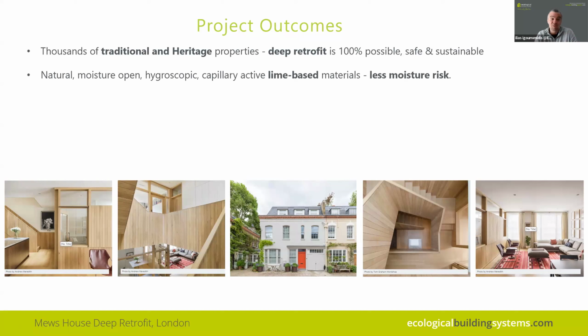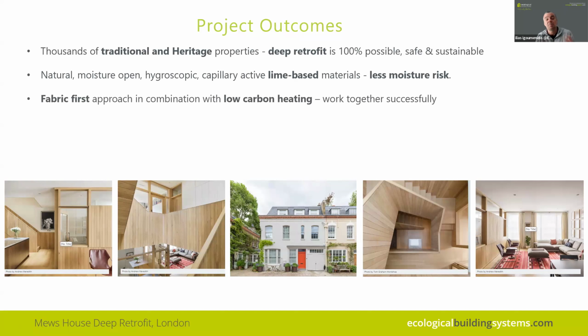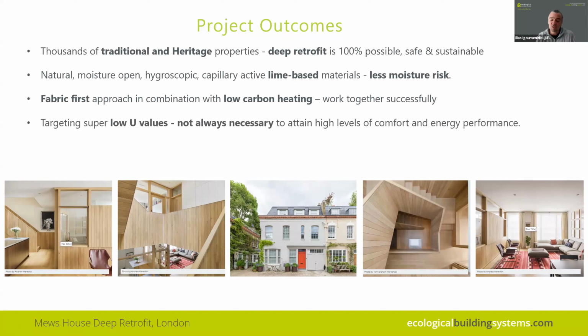Using these types of natural materials, hygroscopic, capillary active, like lime-based materials, to manage the moisture safely. This combination of a fabric first approach added with low carbon heating works very, very well. The obsession with very low U values should be a little bit more modest here. We always need to have a balance, but we are still achieving very, very good results.